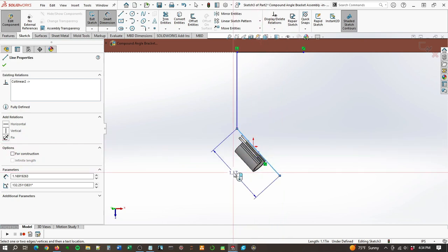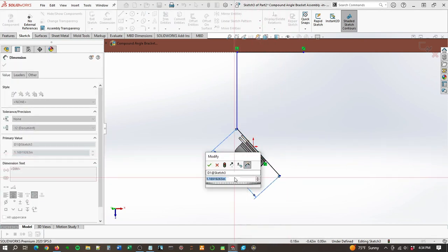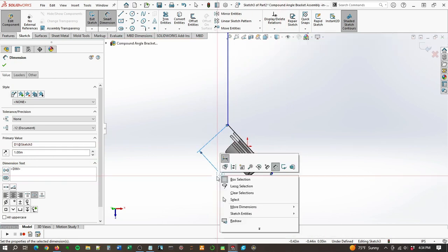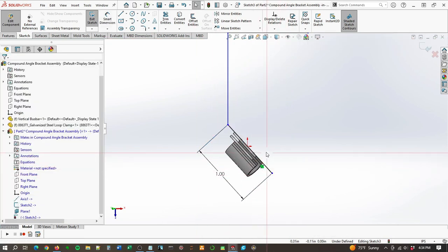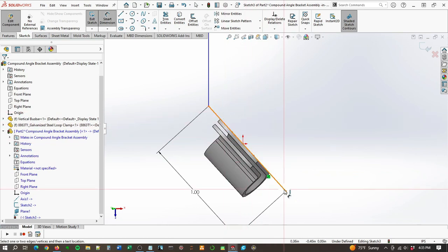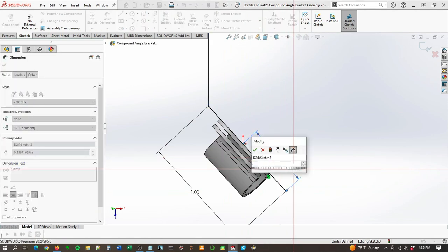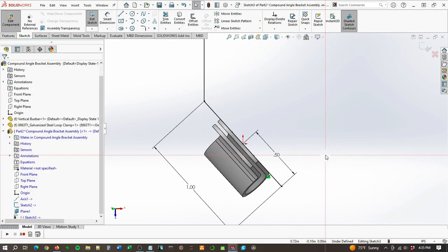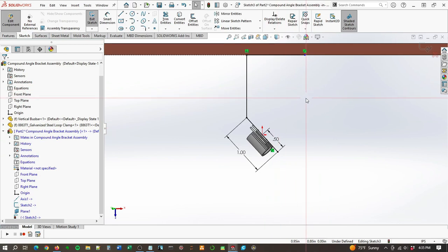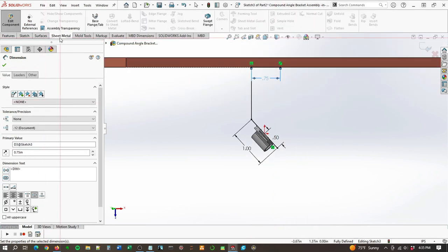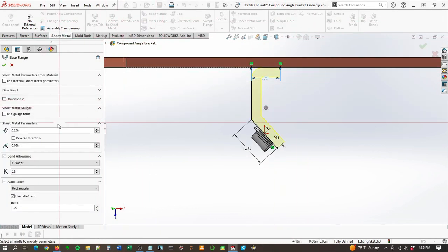I'm doing a little bit of dimensioning here. And this is just kind of rough. I'm just entering in a rough value here, ballparking it. So I'm using the Smart Dimension tool for that. And on my interface, I have that mapped to the D key as a shortcut. Very handy. I just dimensioned that origin point, which was positioned at the center of that hole. Made it half of that 1 inch, just to center it.